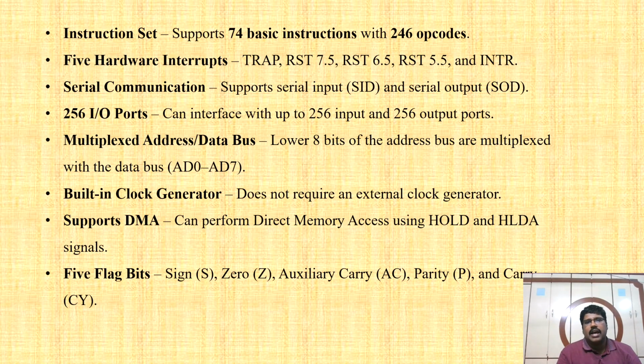Next, it supports serial communication. So there are 2 pins called SID and SOD, the serial input data pin and the serial output data pin. Next, it has a built-in clock generator. It supports direct memory access, and in general, this is the main important part.